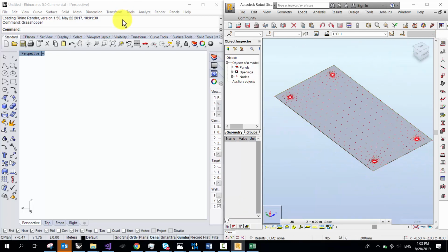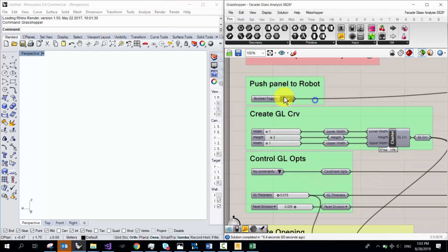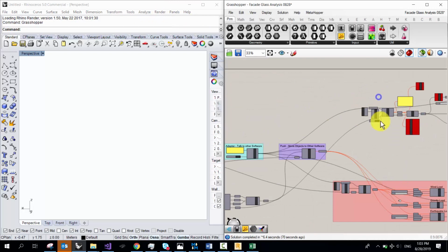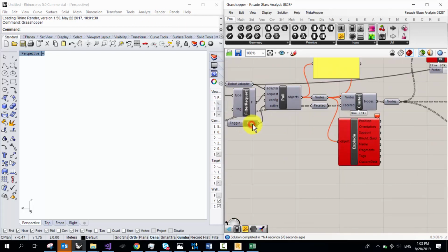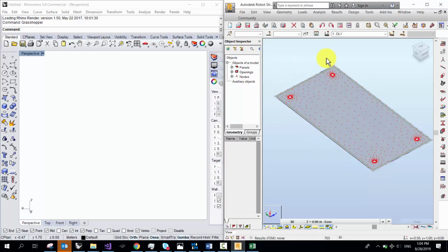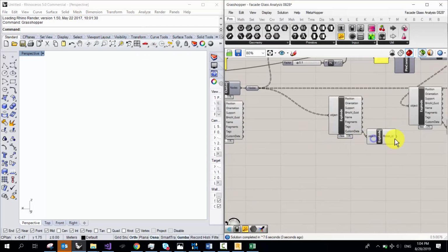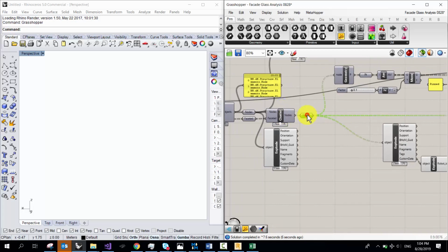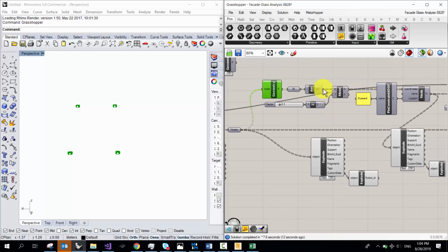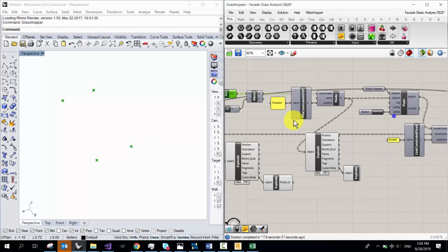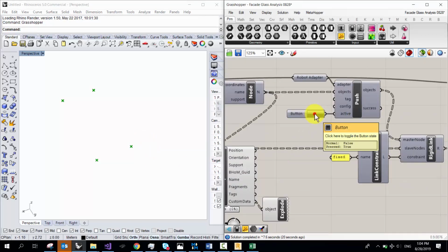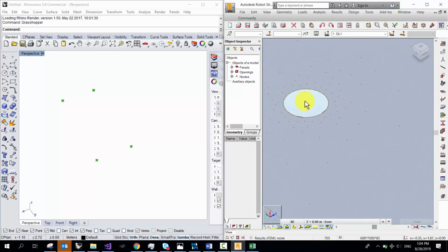This isn't a lesson on Robot, all right? So now we say, okay, it's gone over, turn him off. Let's pull over the nodes. Okay, and this takes a few seconds. All these nodes that we've just created are going over to Grasshopper right now. They all kind of are self-aware in the sense that they have Robot IDs now. Sung has grabbed what looks to be the right guys, and he has created some points in space that are going to be our supports. Now if we press this button, we should see those points show up in the middle here.